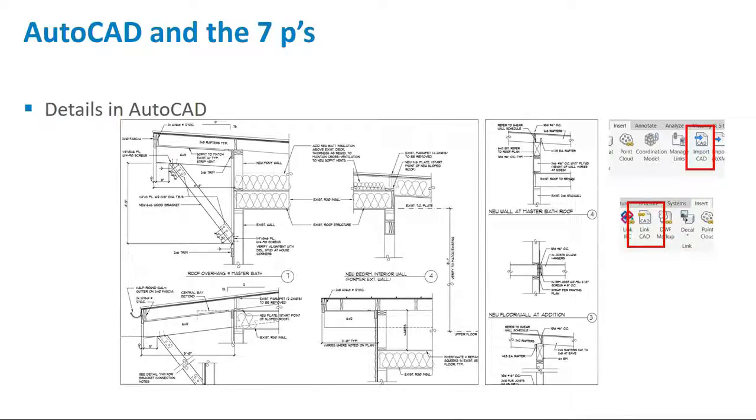If you link it into Revit, one of the nice things about it is that it doesn't bring the whole legacy of the DWG into your project. And I've got another way of working where I'll link it into another project and then link that project into my working project, which means that they are completely divorced from each other. And that would be my preferable way of working.